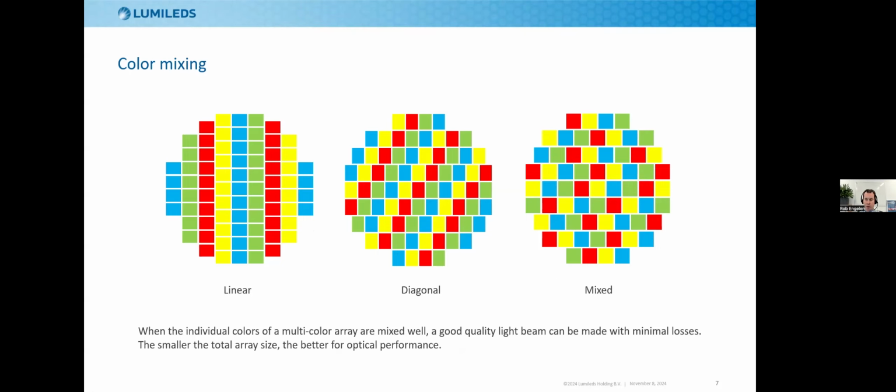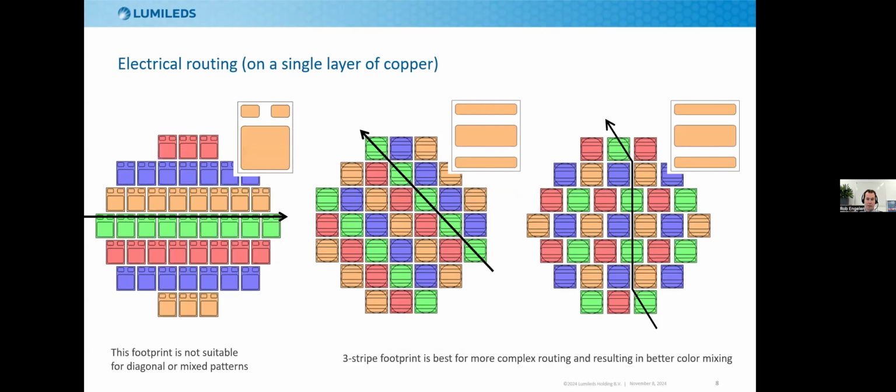So whatever we choose, let's put the LEDs in a randomized fashion. So how to do that and also be able to turn them on. Here I depicted 2 different popular footprints of LEDs. Here on the left, there's the Luxeon ZES, which has a large thermal pad and 2 electrodes for connecting the LED. This thermal pad is isolated, and if it's large, you would think, well, this is ideal for my thermals. But the routing is very difficult.